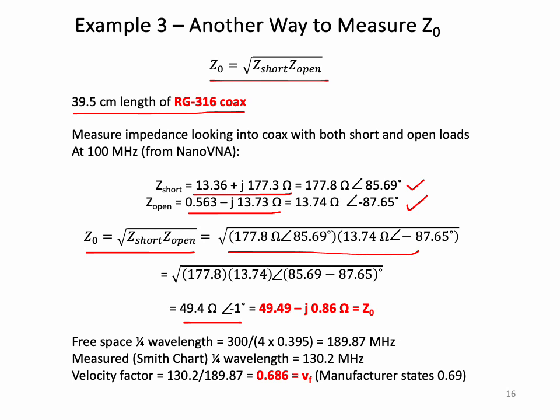Note that in general, the characteristic impedance specified for a commercial cable is only an approximation, and you will often find this impedance is not purely real. Remember, our earlier results would show that for lossless cables, the characteristic impedance was real. However, for lossy cables, again, this is only an approximation.